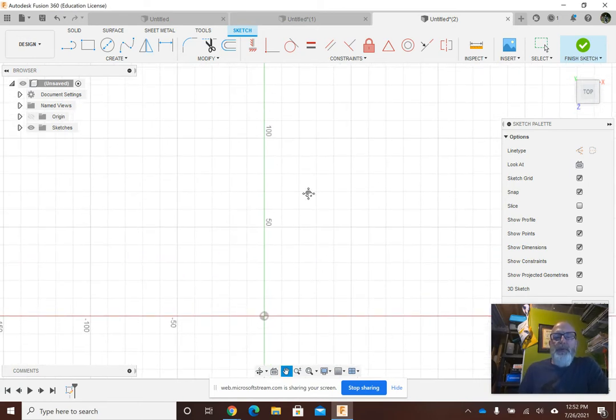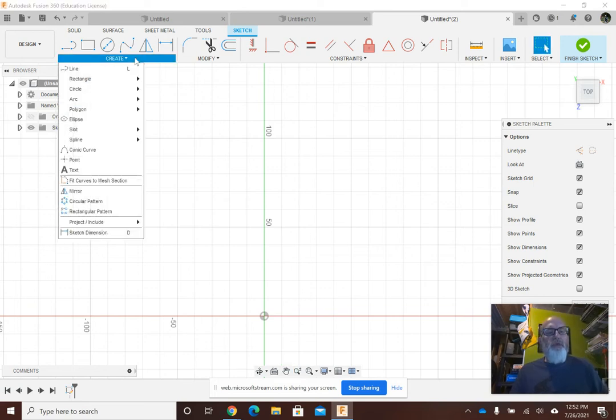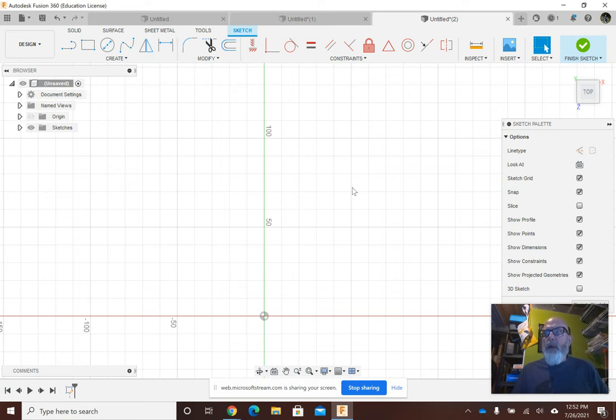take the hand tool here and pan it down. Let's say, for example, we were going to sketch out a baseball diamond. Now, a baseball diamond, a diamond, we don't have a tool for. There's no diamond tool. A diamond is simply a square turned on its corner, an end corner, correct? Yeah, that's a diamond. So we use the rectangle tool, but we cannot use a 2-point rectangle because with a 2-point rectangle, the sides are going to be horizontal or vertical.